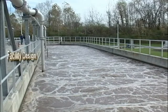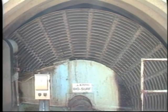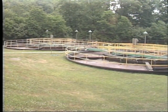Factor number 10, facility design. As previously illustrated, the ability of a system to nitrify may be limited by design. Be sure to review your system design with your engineers if you have questions about design capacity.